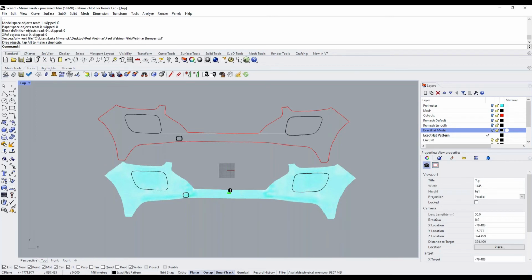If you use the target strain mechanism, it's pretty easy. But if you don't use target strain, are there other ways that you can adjust the size of your template? Yeah, if you don't want to use target strain, you can simply scale your model before flattening. It might be a little more difficult to find the scaling factors required to get the exact amount of strain.